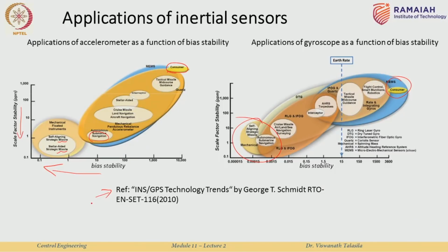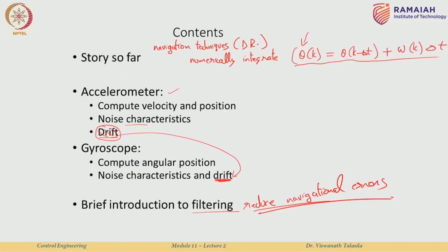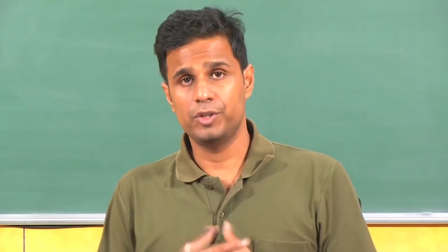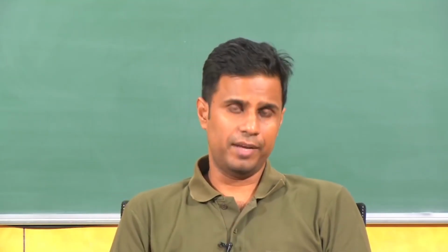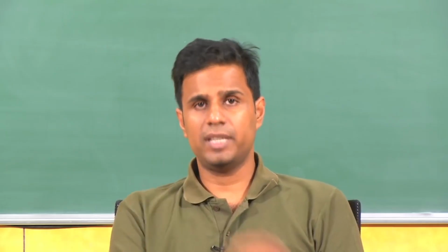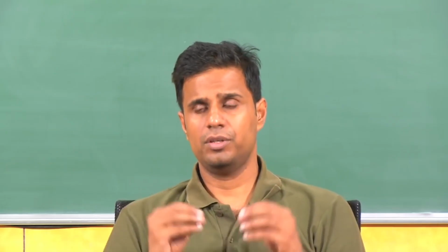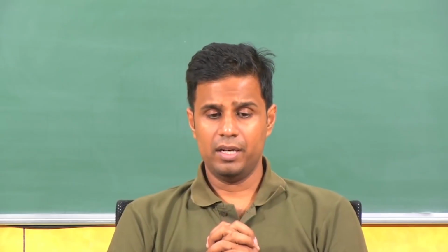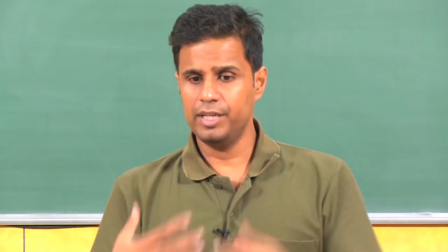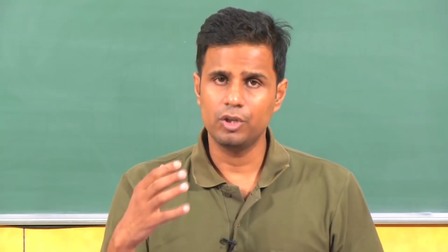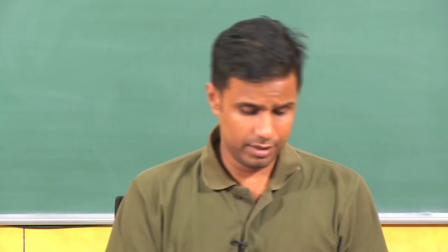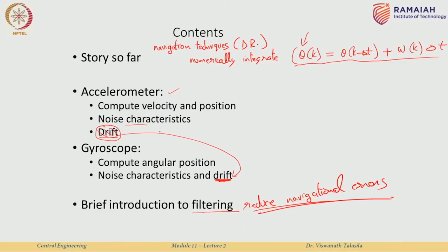So, the point of this entire discussion was that we tried to look at accelerometer and gyroscope noise characterization, while there are plenty of noise parameters which must be considered for really serious navigation. For most consumer type of navigation, it is enough to focus primarily on the constant bias, and where these noise characteristics affect your navigation is in the phenomenon of drift.